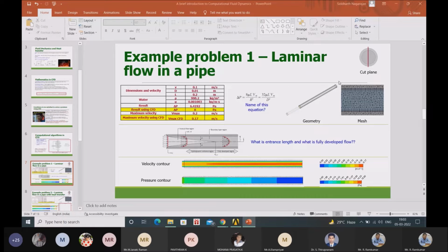So because of velocity here, it will have higher pressure here and a 0 pressure here. So from what I said in the beginning, the difference in pressure is going to make the fluid flow. So that is what is happening. So how do we verify whether our result is correct from the simulation that we are getting? For that, for simple stuff like this, you will be able to do stuff analytically.